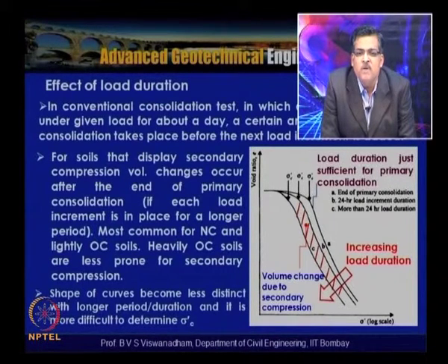So, what we understood is that if you keep the load duration slightly longer, then for over consolidated soils there is a negligible influence, because the secondary consolidation component will be very low. But for normally consolidated soils and lightly over consolidated soils, we can see significant volume changes due to secondary compression. Also, we have discussed that the shape of the curves becomes less distinct with a longer duration, and it is more difficult to determine the pre-consolidation pressure sigma dash C.